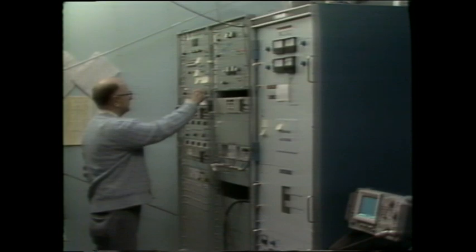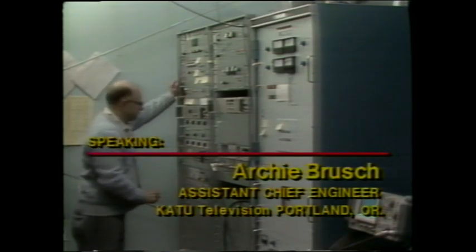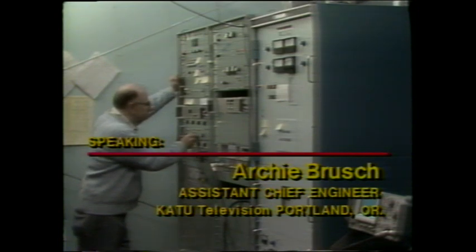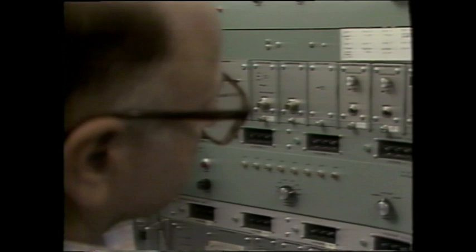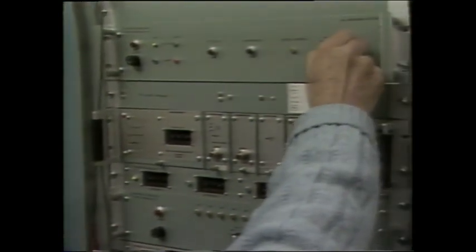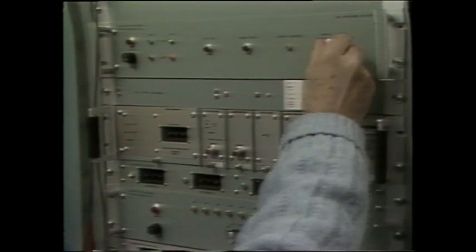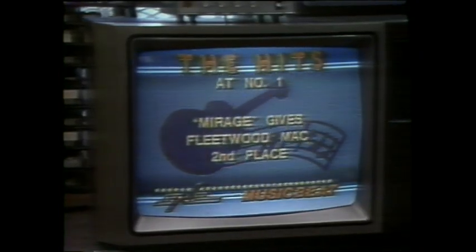I might add that on receive only, the polarization doesn't have to be set nearly as sharp as on transmit, but if I'm off 3 degrees either way on transmit, I'll interfere with a neighboring transponder, and the network people, whoever's running the satellite, would ask me to leave the air until I corrected the difficulty.